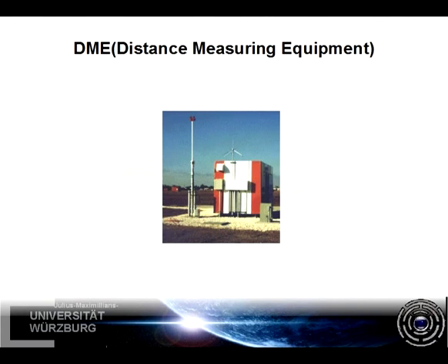So far, we still do not know our position. The VOR allows us to determine relative directions only, at least as long as we do not use triangulation. The other very common way to get a fix on your location is to use a VOR in conjunction with DME, distance measuring equipment. This is how it works.